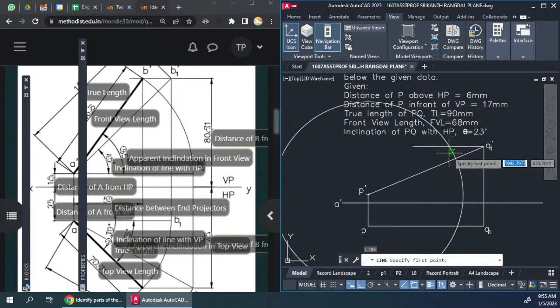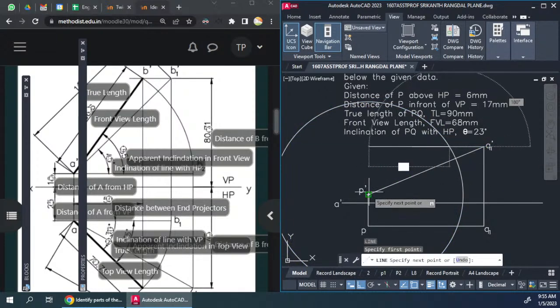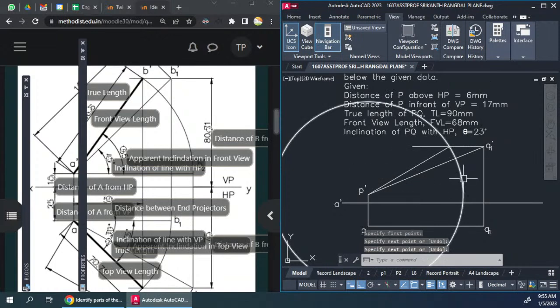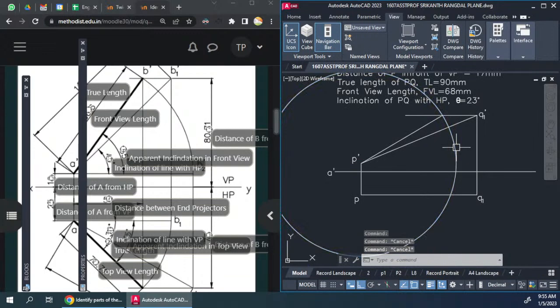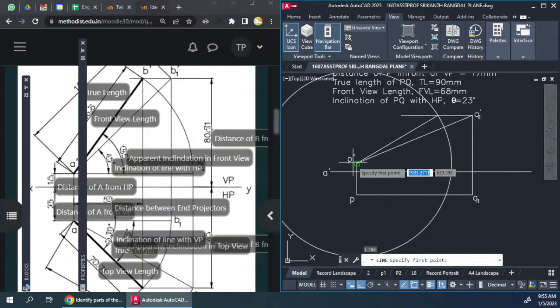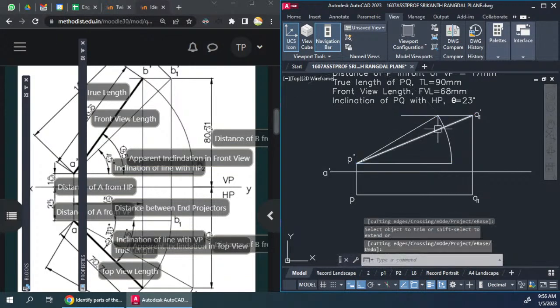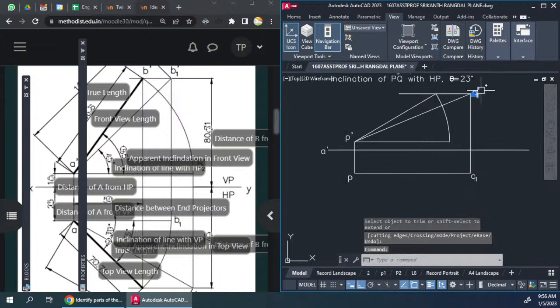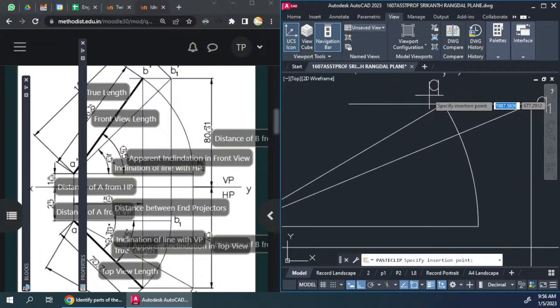So let's go ahead and draw that. The intersection of these two up to here. This circle we might actually keep it. You can see here there is an arc coming all the way down up to this horizontal line. So let's draw that horizontal line and trim the circle which is outside. Okay, so we just need this point as the final point.